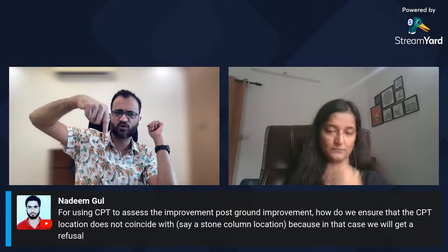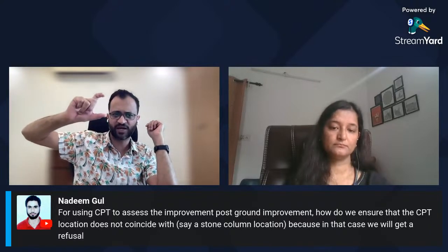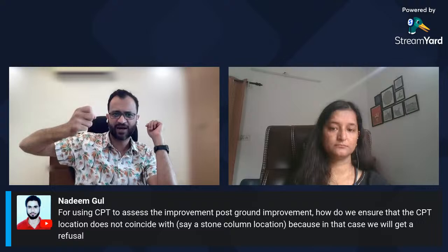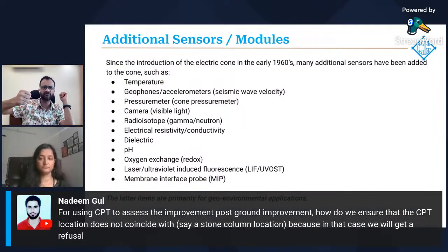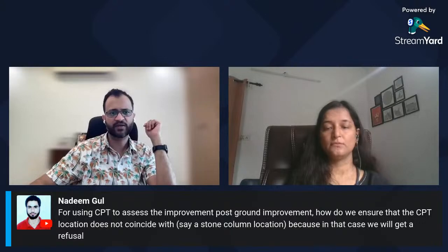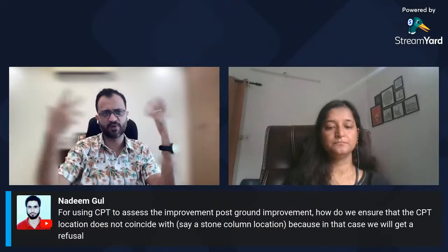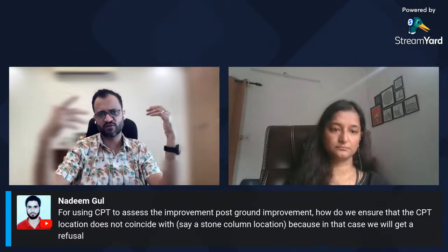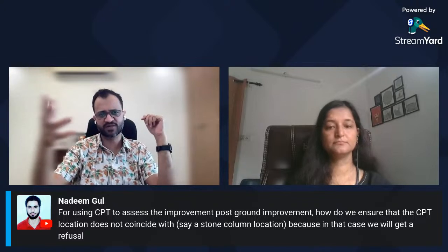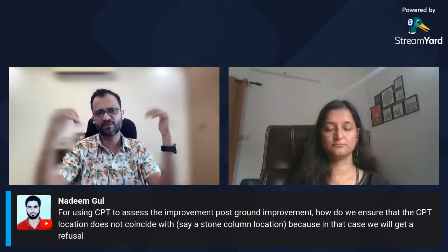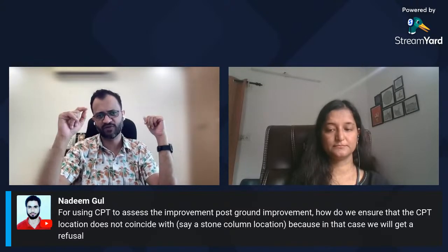But when you're doing piezo cone testing, you are actually measuring the inclination and controlling the cone inclination, and you make sure the inclination is not more than, say, 4 or 5 degrees. So your test is actually fairly vertical, right? And in our experience, when we have done a fair amount of this testing, I think most CPTs would go through full depth without encountering refusal.